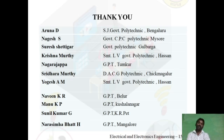Also we have seen the magnitude of EMF induced depends on three parameters. E is equal to BLV sin theta: the magnetic flux density, the length of the conductor which we have taken, and the speed at which we are rotating the conductor. The amount of EMF induced depends on these parameters. So based on these discussions, let us end this particular session.